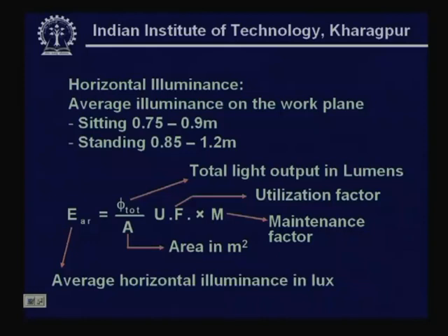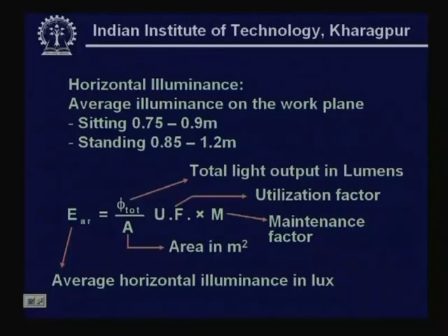The second thing is, we have seen for different types of lamps, there are what are called the mortality curves, or with age there is a depreciation in the light output, and further it is accentuated by the maintenance procedures, where periodic cleaning and dusting becomes very important. Otherwise, dust accumulation is one aspect which reduces the output.